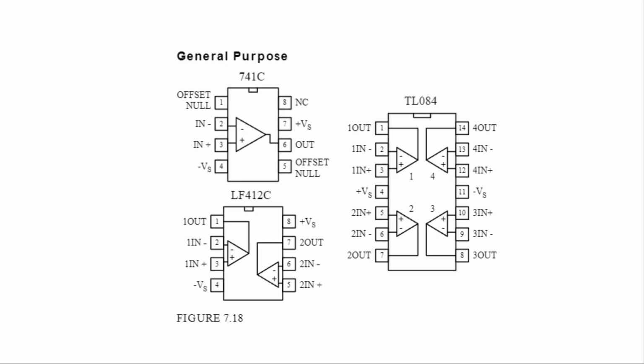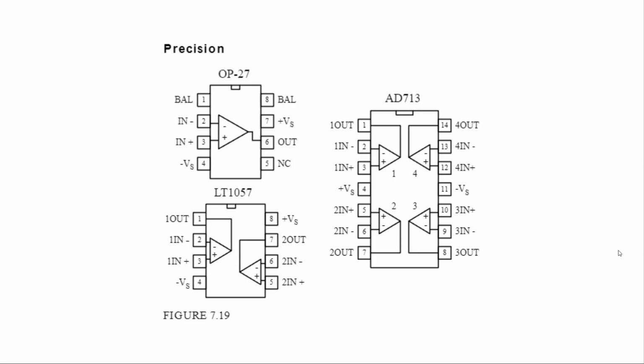Input bias current can result in voltage drops across resistors of various networks, which in turn can offset the output voltage. So the amount of offset a circuit can tolerate depends on the application, but usually you want as little as possible. Next, for those precision op amps, a simple way to avoid problems associated with input bias current is to use a FET op amp. A JFET op amp has a very low input bias current.